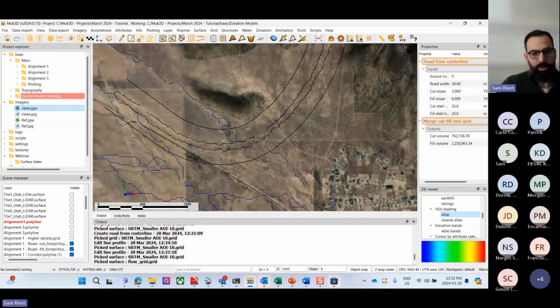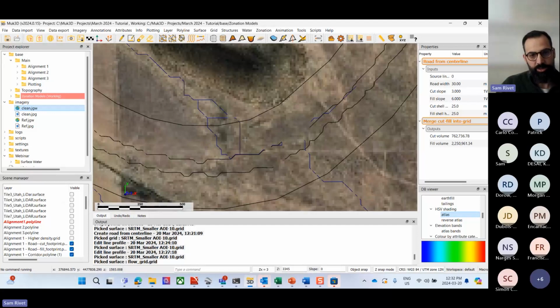So what I'm going to want to do is lay out an intercept ditch. I want to cut off this water, and I'm going to bring it to a water storage area. I'm going to place that all within my right-of-way, but outside of my footprint.